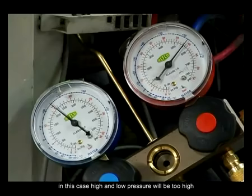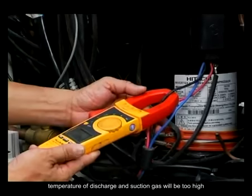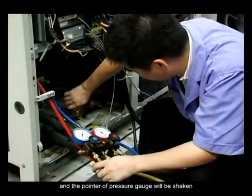In this case, high and low pressure will be too high. Temperature of discharge and suction gas will be too high. Current will be too big. Compressor maybe has abnormal noise, and the pointer of pressure gauge will be shaken.